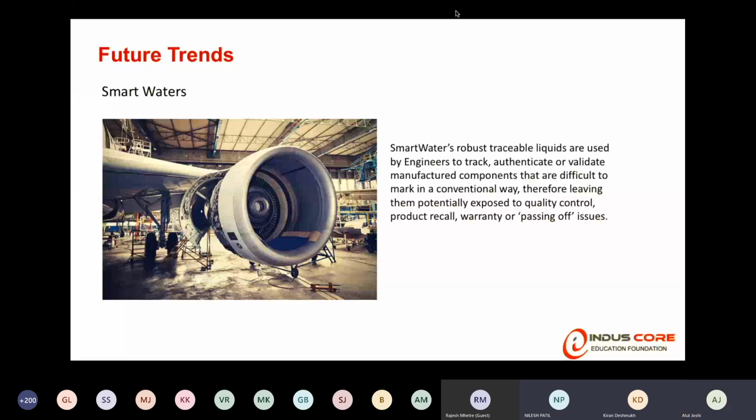Yes. So as I said, if you're trying to use, for example, RFID, right? Now there are two types of RFIDs. One is called active RFID, which keeps on emitting its own signals, and there are passive RFIDs, right? So active RFID has a lot of limitations in using in aviation systems because it can affect the navigation systems inside. So we face a lot of issues when it comes to such kind of implementation.